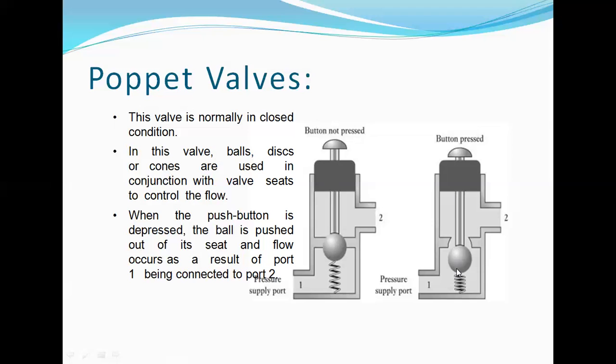entered pressure will be changed into the tension that has been compressed in the spring, and hence this will be a stopper in the open condition. The movement of this gaseous medium, that is compressed air, or else fluid, will be moved to the second port. The entry is port 1; pressurized fluid or gaseous medium enters by port 1, and when it is in the pressed or external pressure applied condition, this will move towards the second port. The supply will be at the second port.